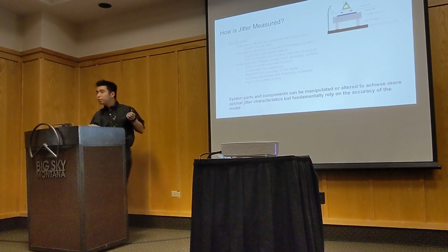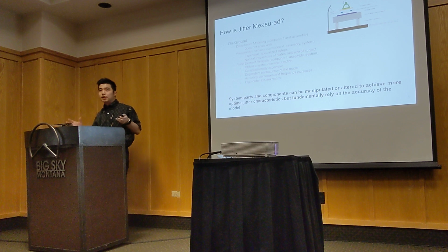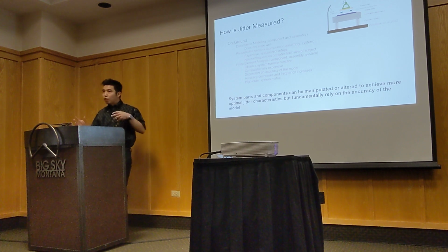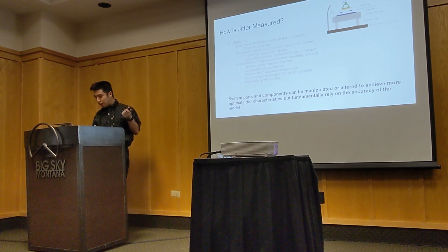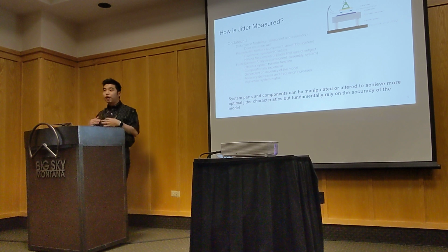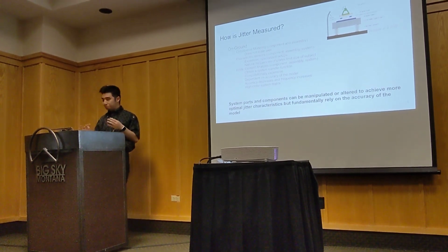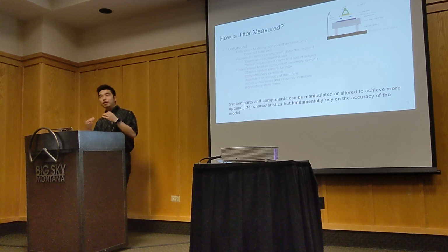And these plates often limit the size of the subject that you can measure, as well as the frequency that you can measure up to. Once you get the disturbance data from these piezoelectric sensors, you move on to finite element analysis, where you obtain a system transfer function, which is usually based on a finite element model.